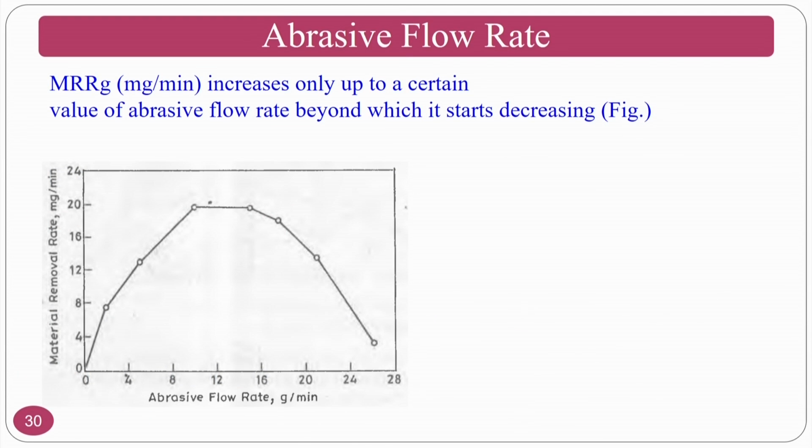So, the flow rate, if you see the output responses, that is how abrasive jet machining works, the MRR increases only up to a certain value.